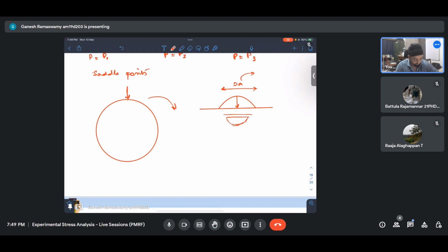In which case, a point that is somewhat below the load application point acts as the source of the fringes coming out. So this essentially represents the point of maximum stress, not the load application point. Now, if I make my material more and more rigid, my A will keep on coming down and this will keep on shifting to the surface, but it will still be somewhat below.